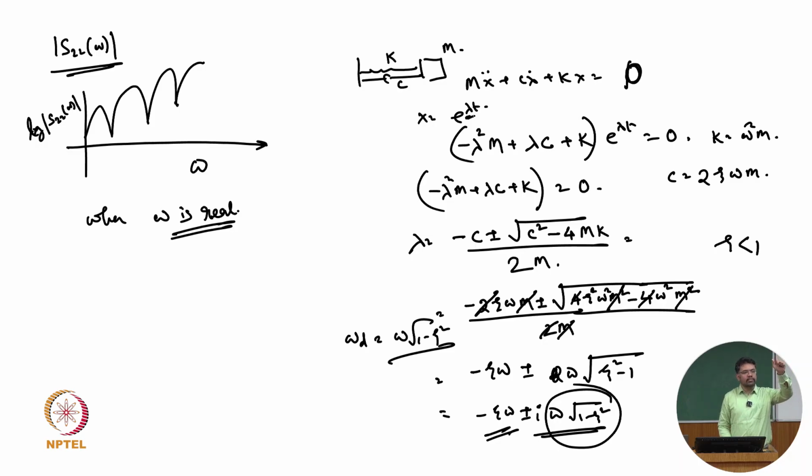That omega becomes complex. So if there is damping present in the medium and we try to calculate the exact natural frequency, we will get it complex. What do we do generally? We generally do not go this way. We say, forget the damping, solve with the mass and stiffness, get omega, and multiply with root over 1 minus xi square. But where did the root over 1 minus xi square come from?